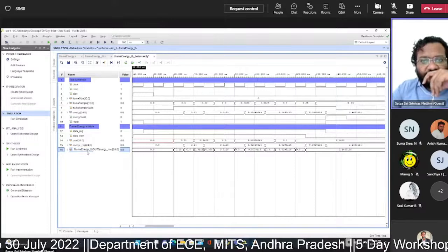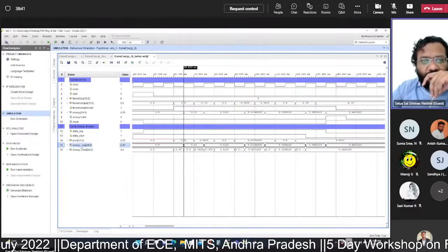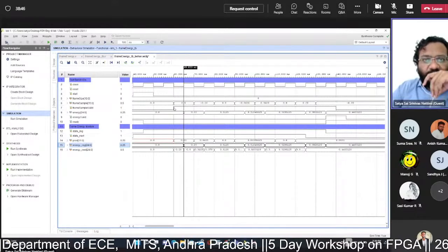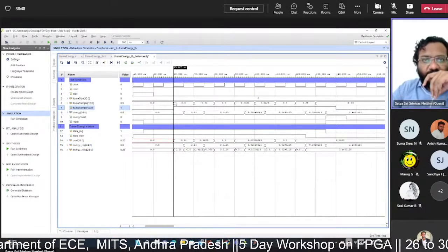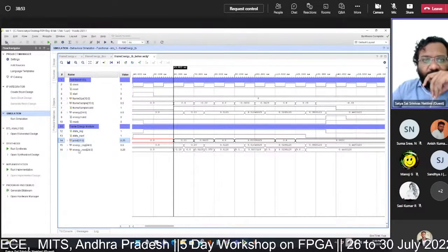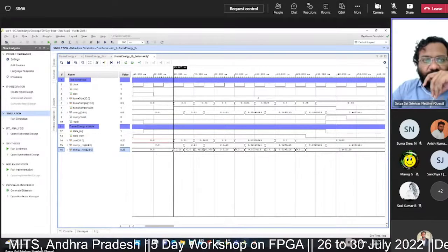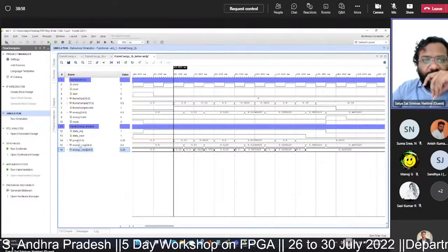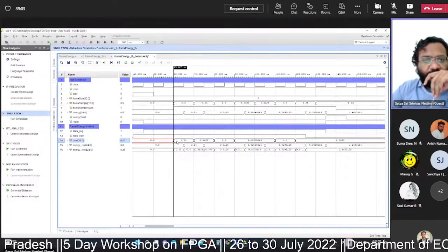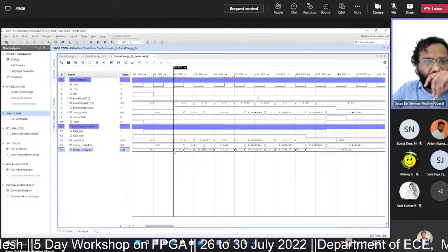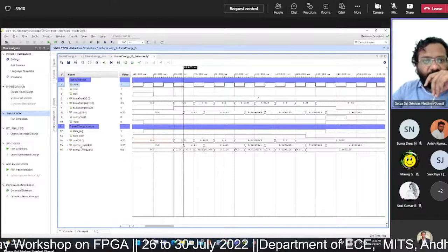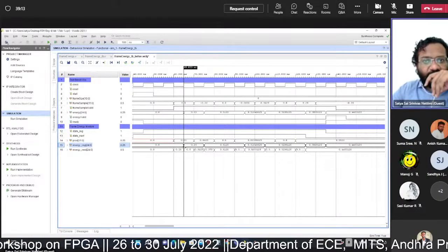Forget about the next state logic, it keeps on fluctuating; only take into consideration the register value. Earlier, when you gave the value 0.5, the product value is computed as 0.25, and the energy next value is calculated as product plus current value. The current value in the register is 0, the product value is 0.25, so ultimately the end value is 0.25. This computed value will be updated in the register on the next arrival of the clock edge.